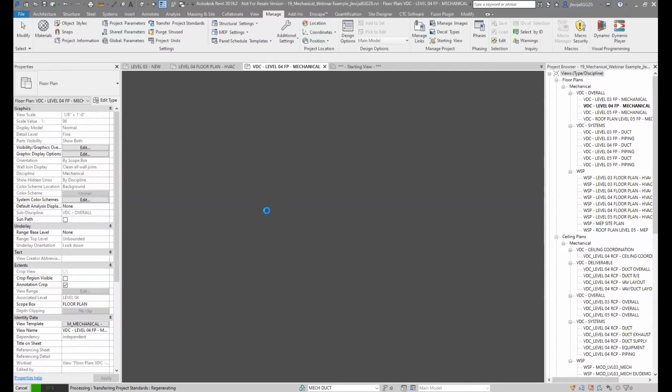And if you've only got 1 or 2 types of VAV boxes in this project, just bring 1 or 2 types of VAV boxes into the project and then scrap out everything else. That way you're not overkilling your model size.